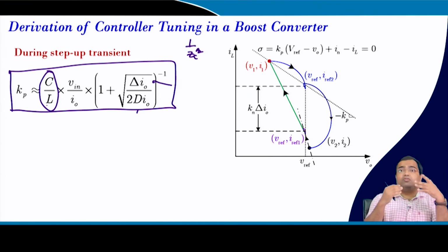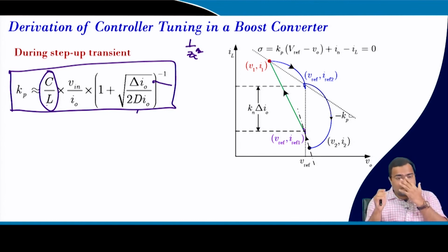We generally do not go for actual sensing of load current, though for a boost converter the load current is somewhat lower, because you are going for high voltage low current application, but still it is not very much recommended. We can use an estimated load current algorithm.